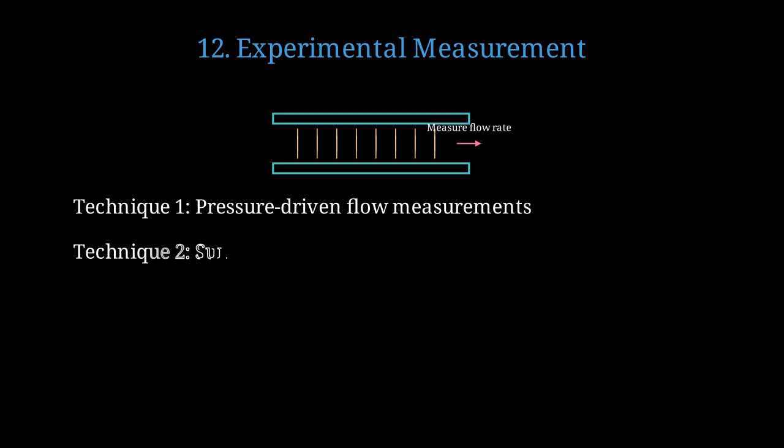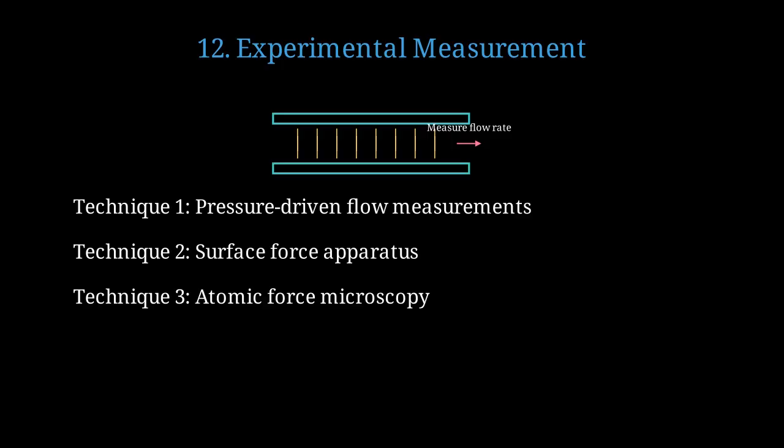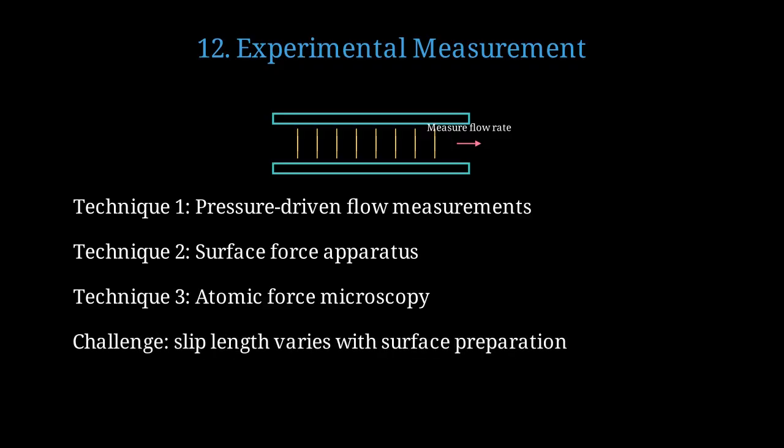Surface force apparatus can measure forces between surfaces separated by nanometer gaps, revealing slip through drainage rate measurements. Atomic force microscopy can drag a probe through confined fluid and measure drag forces, which depend sensitively on slip. A major challenge is that slip length is extremely sensitive to surface preparation, contamination, and even dissolved gases.